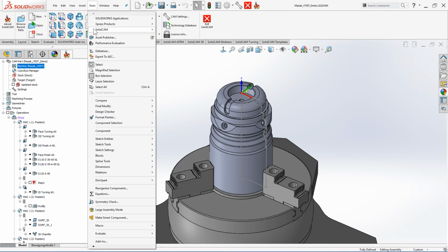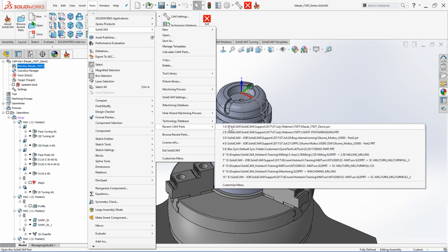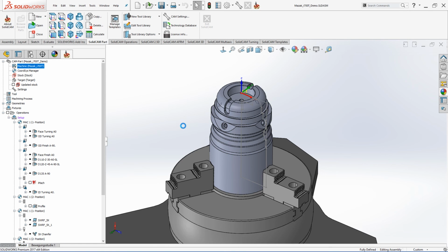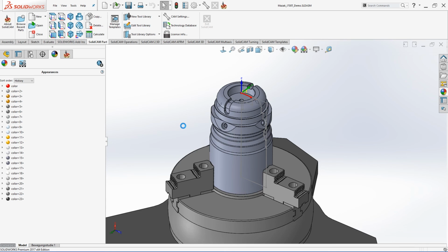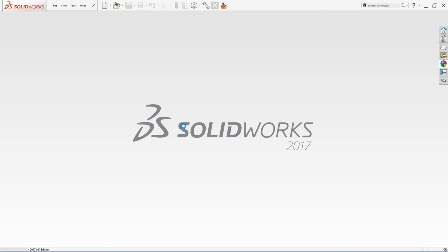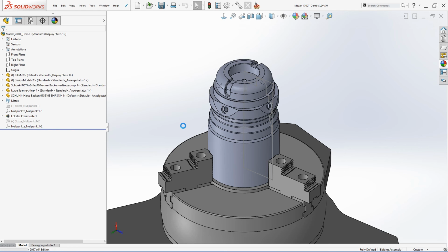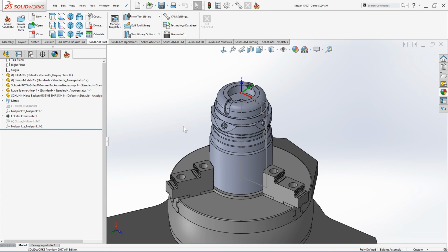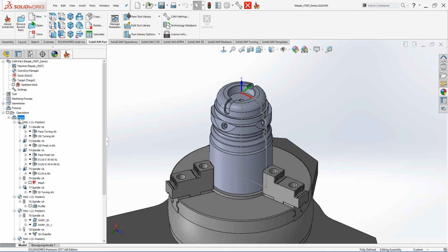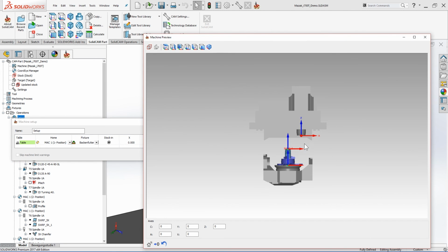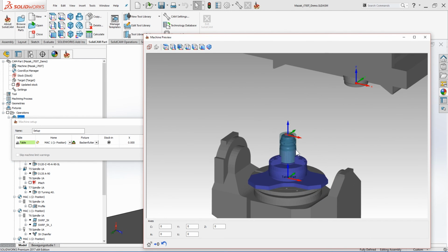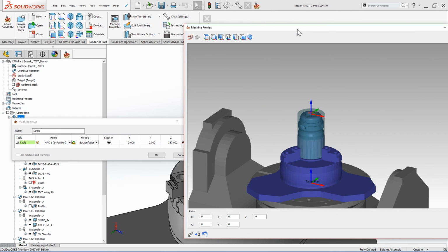What I have to do is go to SolidCAM itself and reopen this project. This way, the XML file that we just defined with all the geometries inside will be loaded in our machine preview. Now the users can use this function. Okay, I'll go to the setup itself, machine preview, and our STLs have been loaded over here, and we can now see everything very nicely.